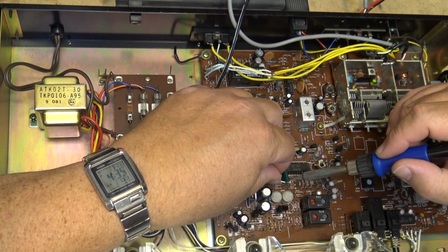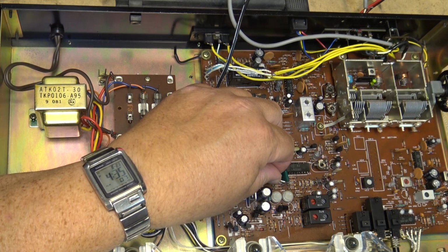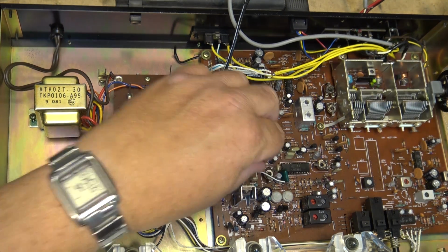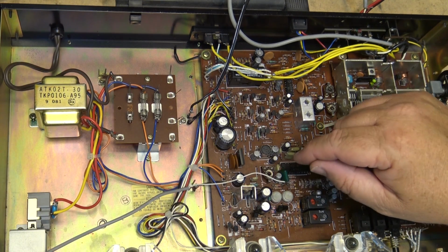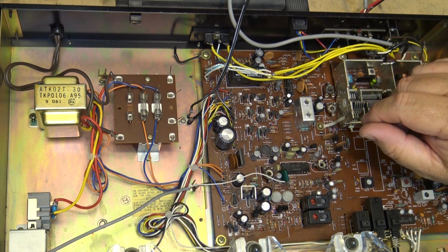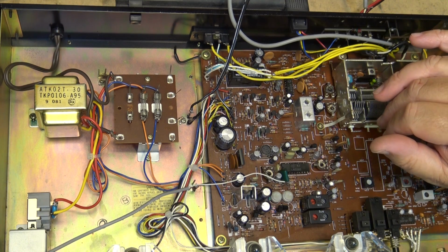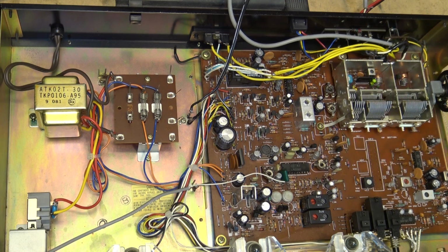And hook it up to my capacitor that I put in here just to isolate, so that I'm not connecting the antenna directly to the output of the discriminator. And we're going to move in now, and we're going to hook this thing up, and I'll show you guys how to tune this stuff in and what's there, and we'll scan up and down the band and see if there's anything else. I think there's only the one station, if I remember correctly. There's just the one station that has SCA on it now, so we'll go and take a quick listen to it.